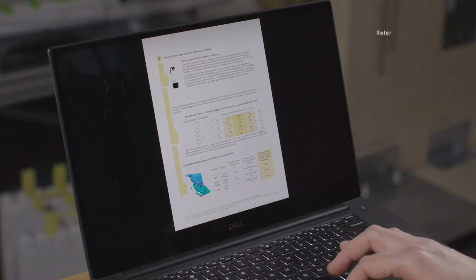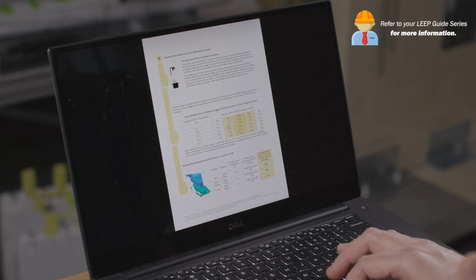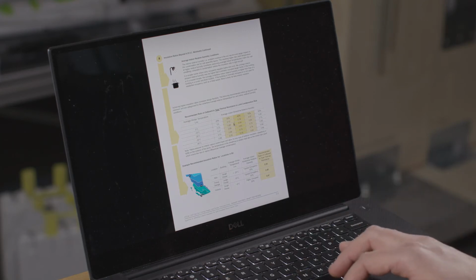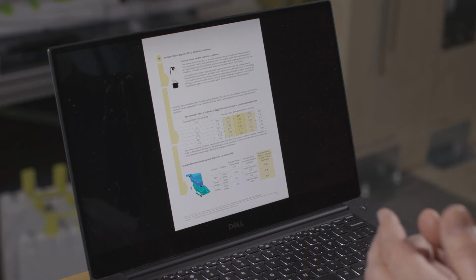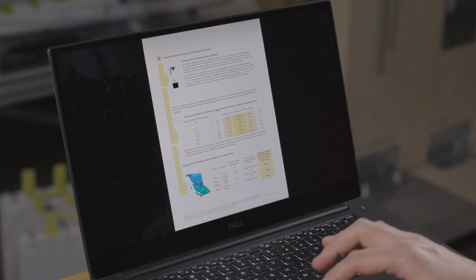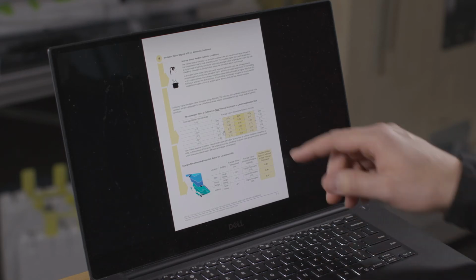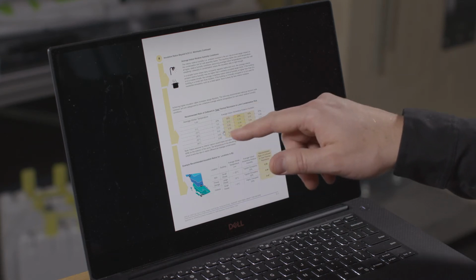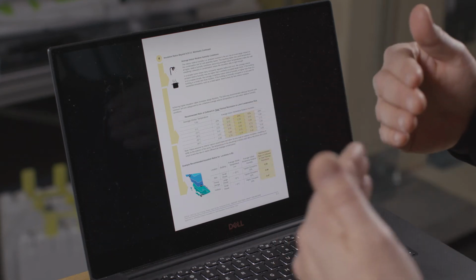And that means that I should have 50-50, R20, R20. That's what a 50% ratio means. Likewise, if I'm in a colder region, the humidity is going to be a bit less in drier parts of the country, and especially when it's minus 20 or minus 30 outside, the humidity is just not going to be at 50%. It's going to be 30%, maybe below 20%. If you're humidifying the spaces, generally it's between 20 and 30%. And so you can see here, the colder it gets, generally the more exterior insulation you need.